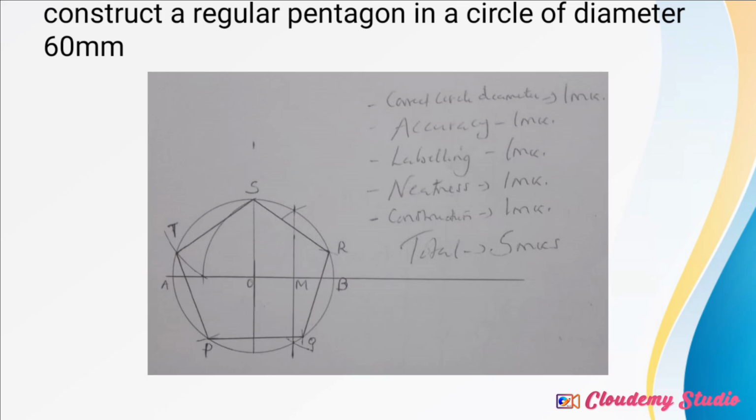So the first step, you have to draw the circle with the radius O. Of course, you've seen for me, I've drawn a regular circle with the radius O. Bisect the circle into 4 equal parts or 4 equal quadrants. After that, you can bisect either one side of the quadrant or one side of the radius. So for me, I used point OB.